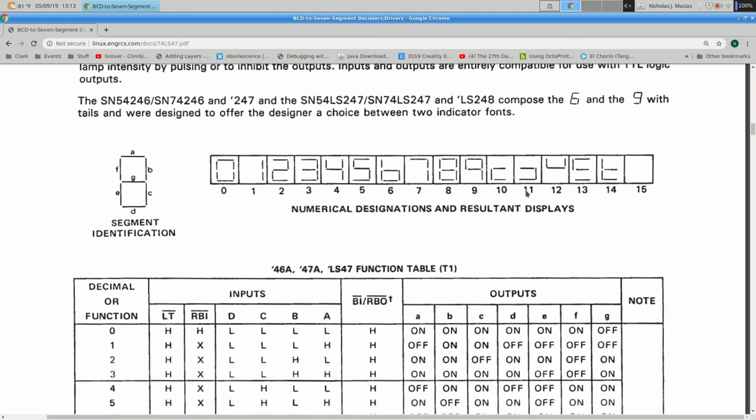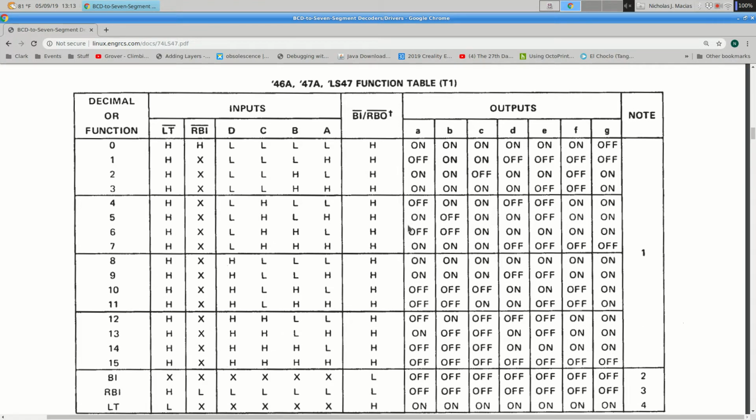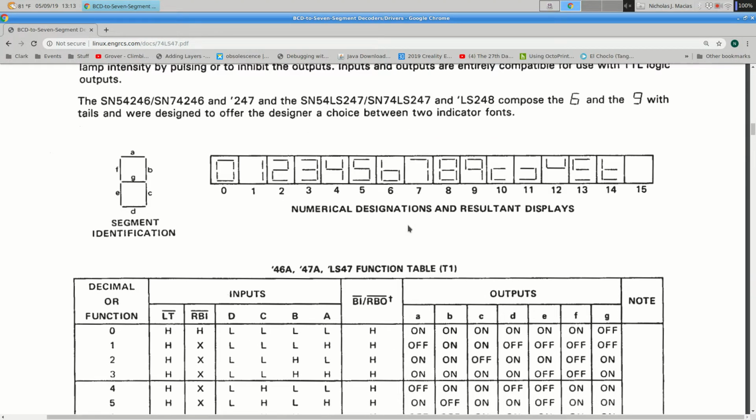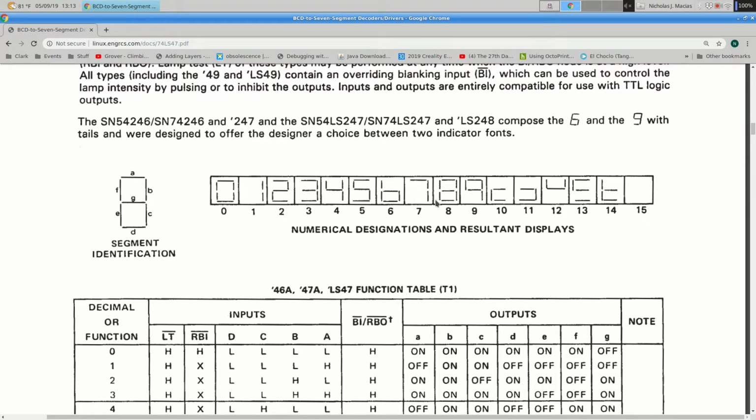And if you see these kinds of symbols popping up, you didn't connect D to ground correctly. So we're basically using this like something that converts a 3-bit number to one of these displays, right? Which means we're ignoring the second half of the possible inputs, which is where D is 1. All right, other questions?